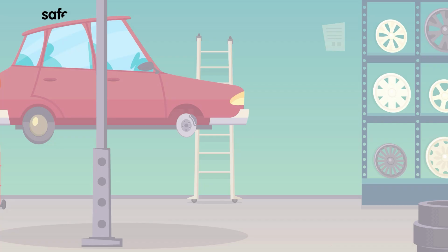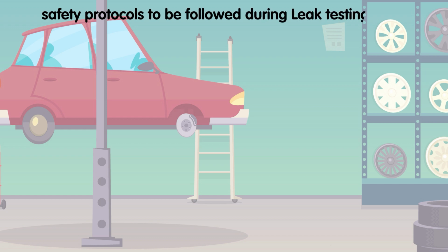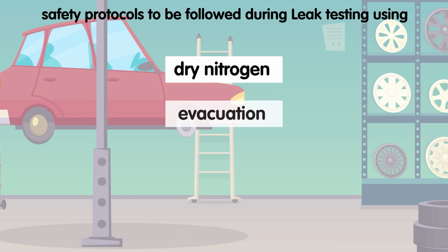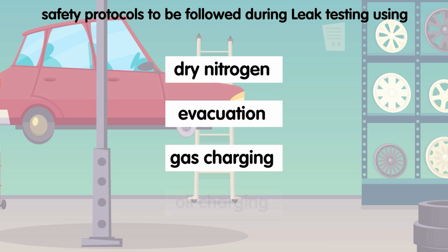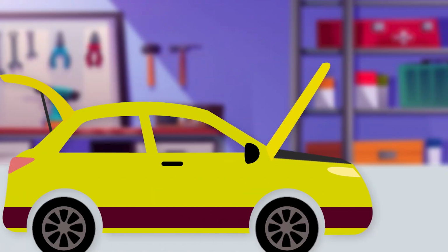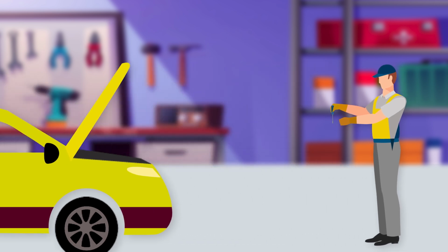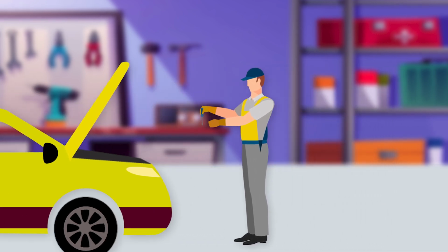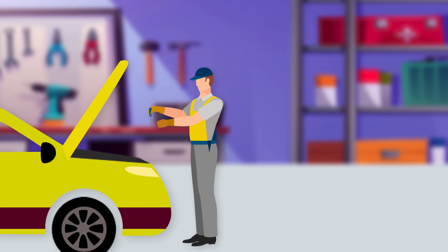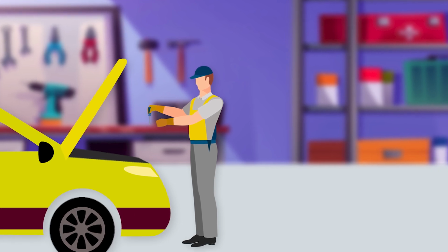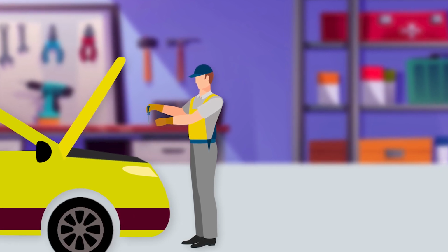Now, let's see the safety protocols to be followed during leak testing using dry nitrogen, evacuation, gas charging, oil charging. When servicing a car's air conditioning system, it's essential to wear the appropriate protective gear to safeguard yourself from harmful chemicals, refrigerants, and potential hazards.